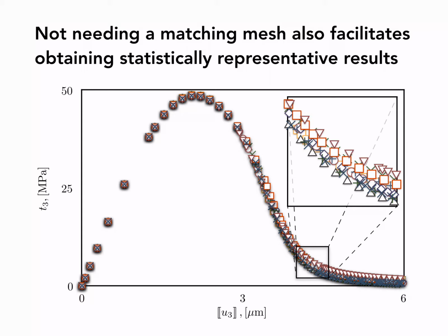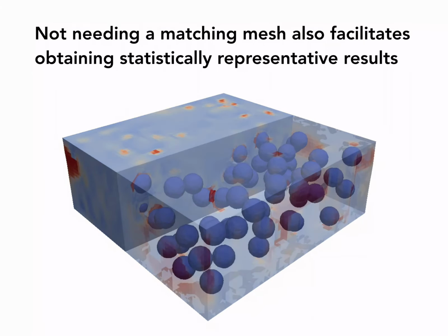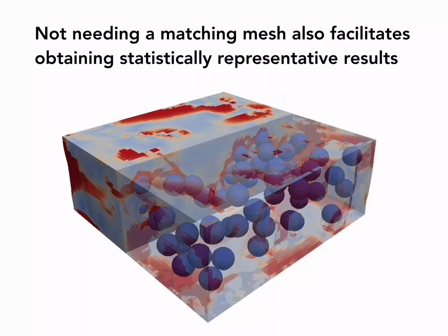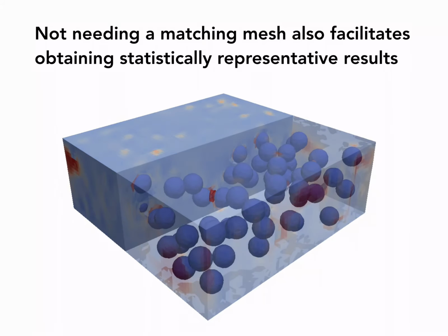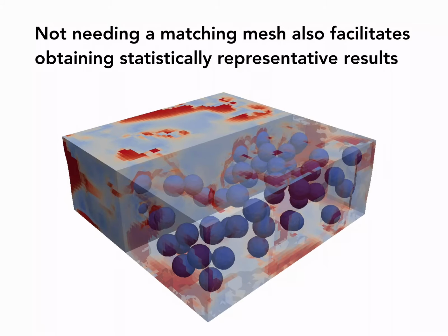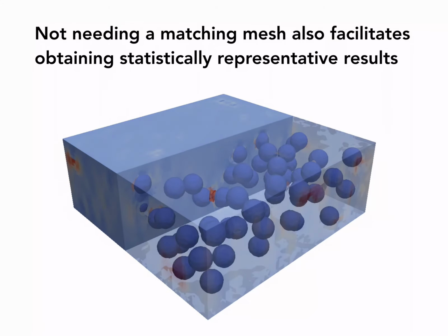So the idea was to investigate what happens to that microstructure when you are actually deteriorating the matrix. So the spheres remain elastic, but if I wanted to have a failure law for the matrix, what happened? And so this is a cool simulation where I'm basically taking this microstructure and I'm applying an in-plane shear strain to it, and then I'm pulling it in mode 1, so in opening mode, and then you see how the failure is distributed in the whole microstructure.